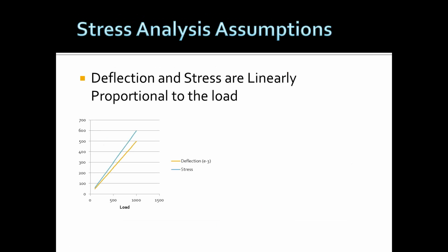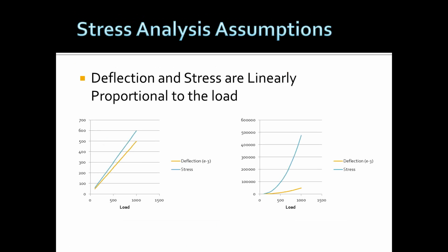Even wood material can be linear in a very small area, but when you deal with plastics and polymers and rubber materials, no, those go into a non-linear classification. So what does that look like? The nonlinear graph, if you did the same thing and the diving board was made out of plastic, 100 pounds would deform it X amount, 200 pounds deform it a higher multiplier of the first amount maybe. As you started plotting points, it wouldn't be a straight line. It would actually curve. And it could even curve not just up, but even return and come back down.